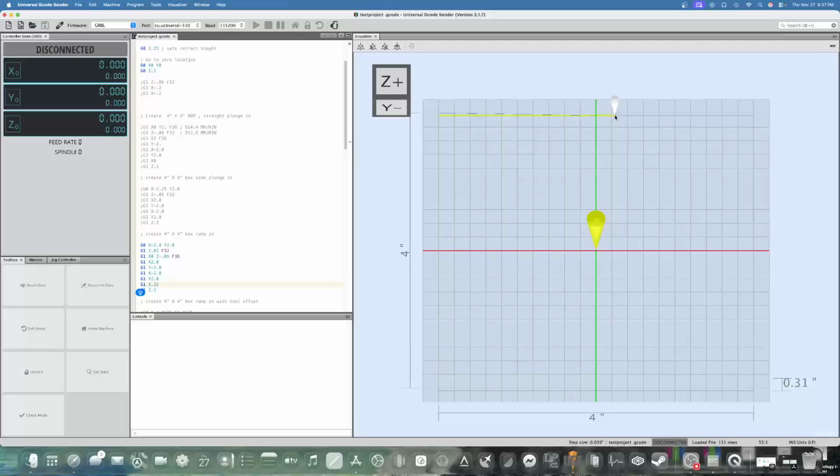But if you overlap it a little bit, you're just guaranteed to clean up any bounce or any overlap that tool might have had, and then feeds back up out the way. That just ensures the face of it when you get cutting with it. When you do that, you'll notice a little spot right there if you don't go back over and travel across it. That just cleans that up.